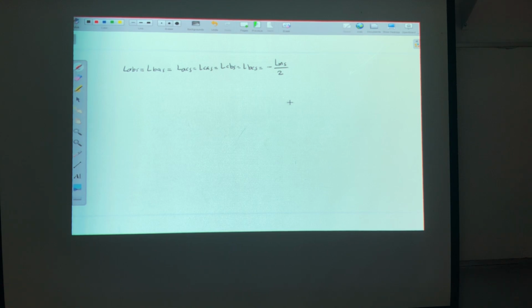And we know that LMS will equal NS squared over the reluctance path, RM. If I need to calculate it, it will be the effective turns of the stator squared over the reluctance path. Good. Now, what about LSR?